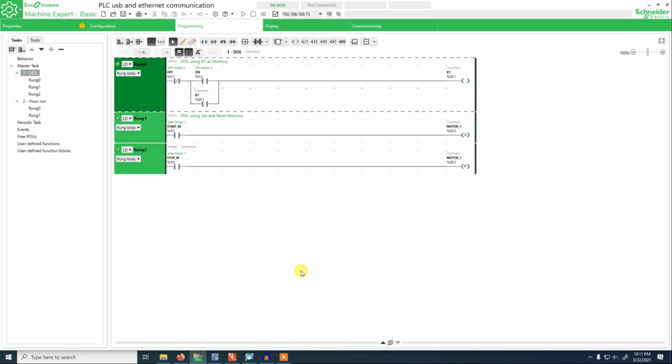How to add an HMI to a PLC so that we can have status of devices like pump running, if pump is faulty. So all this information can be accessed via an HMI via Modbus communication. So this is a basic program which I have made before. You can have it in the other videos.